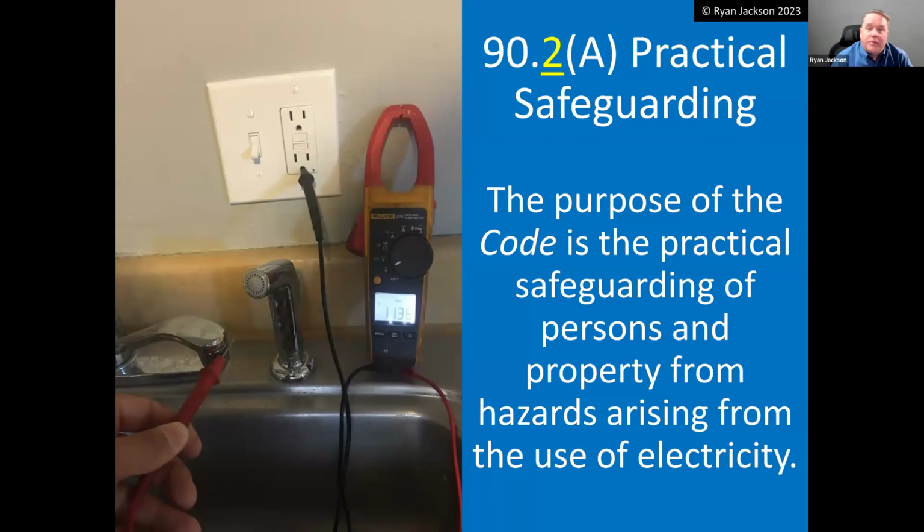And of course, mainly when we talk about the hazards from electricity, we're talking about electric shock and we're talking about fire. So here in this picture, we're measuring roughly 120 volts from the grounding terminal of that receptacle to the metal parts of the sink. Obviously something is extraordinarily wrong in this picture, and it's almost funny because it's so wrong it's almost comic book wrong, but unfortunately it's a real photograph, and this is the type of thing that we're trying to address in the National Electrical Code.